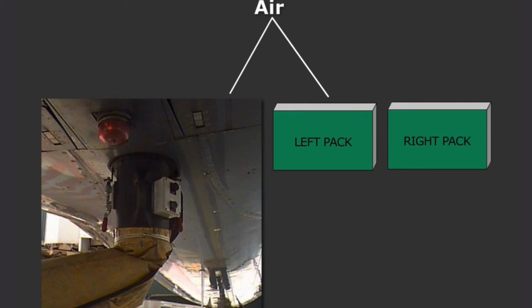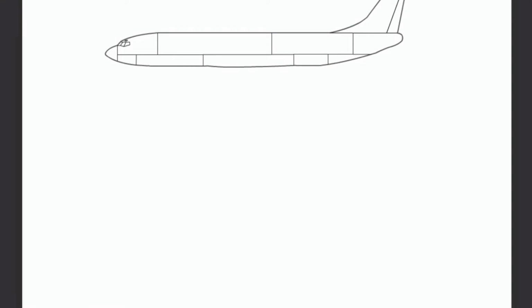Conditioned air for the cabin is provided by either the airplane's air conditioning packs or from a preconditioned ground air source. This conditioned air is used to control temperature for the flight deck, cabin, cargo compartments, and equipment cooling. Pack control, zone temperature control, cabin air recirculation, fault detection, and overheat protection are all automatic.